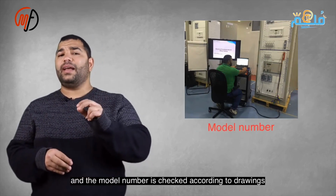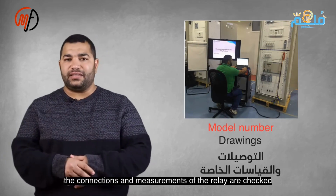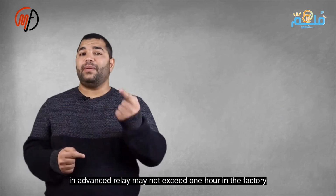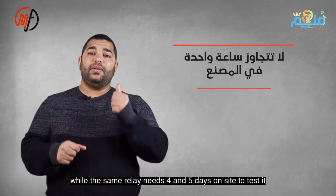Ideally, a commissioning engineer familiar with panel intricacies should witness the test. A common mistake is sending a project engineer who may lack detailed knowledge of these tests. The testing duration for an advanced relay is limited to 1 hour in the factory, while the same relay may take 4 to 5 days for testing on site.